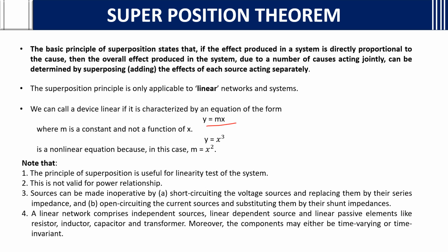Here in mx, we are not disturbing this x. It should not be a function of x. If it is 2x, okay. 3x, okay. It should not be x square, then it will not be a linear function. So if you want to apply the superposition theorem, the network should be linear.